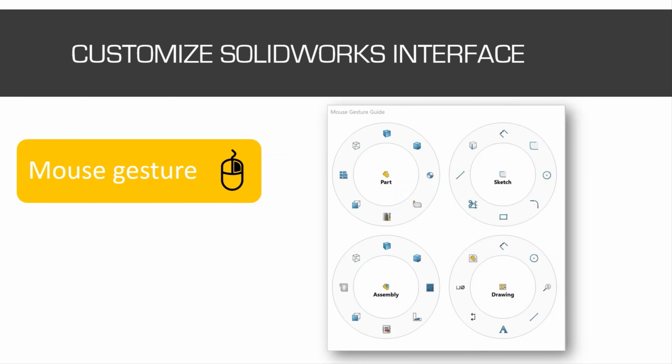So then some options to customize the SolidWorks interface a bit and to work easily with SWOOD and SolidWorks. As for the mouse gesture, as you can see here, you have a quick overview of what I'm currently using and what helps me to work faster. For example, at the part level, you have some settings such as creating new program settings, creating the origins, to have different views with only the edges or the full one. At the assembly level, you can create a nesting directly from there, manage all the material and the edge bands on the left, the connectors on the bottom right, and generate reports at the bottom. Those are the major features that I can use with the mouse gesture really easily and really often.